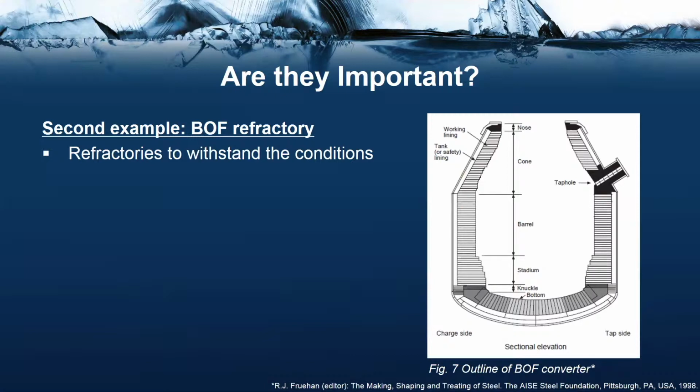The linings used in the BOF converter range from pitch-bonded magnesia or dolomitic types to the advanced refractories that are made with resin bonds, metallics, graphites, and sintered and/or fused magnesia that can even be 99% pure. These refractory bricks are designed with a combination of critical physical properties to withstand the high temperatures and rapidly changing conditions throughout the blowing cycle of the BOF.